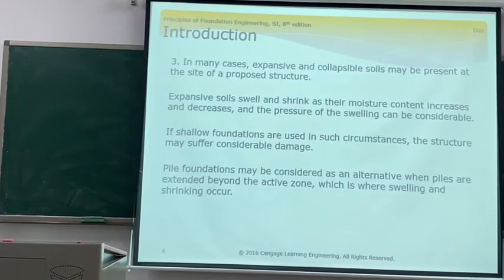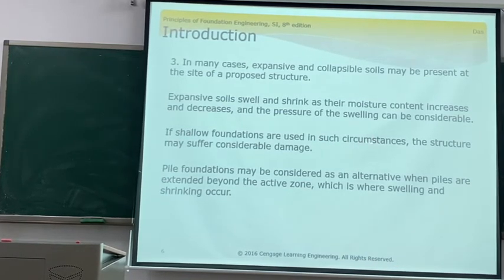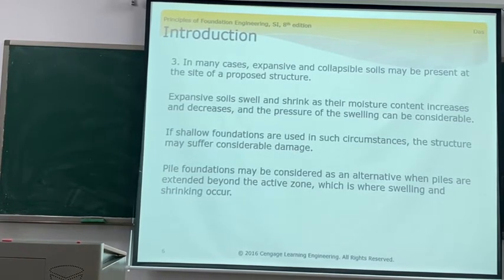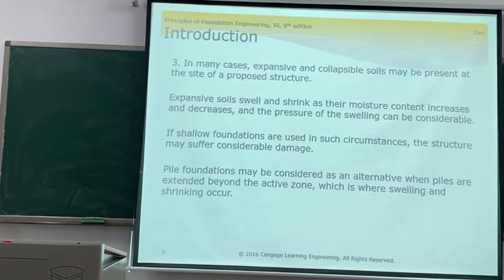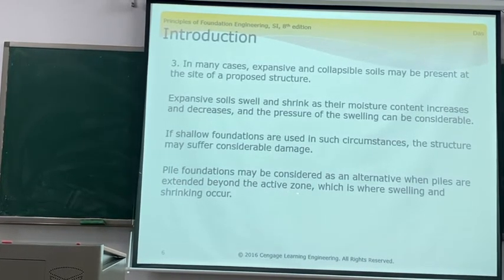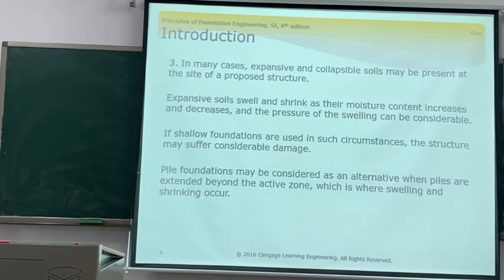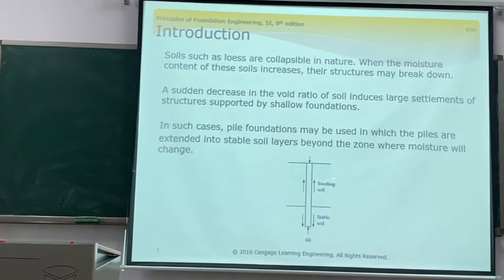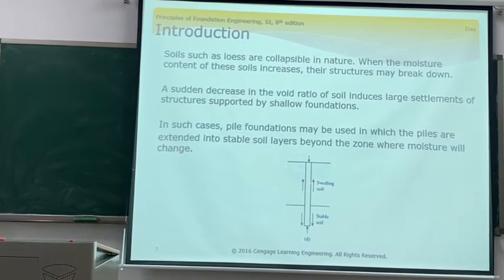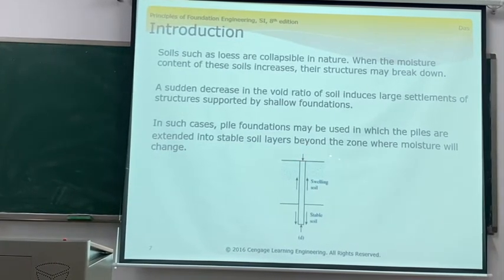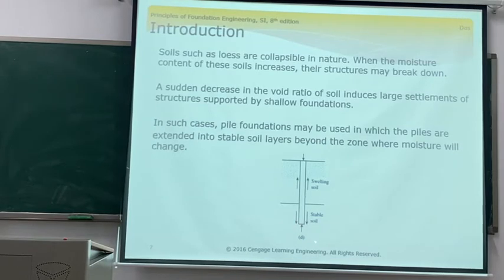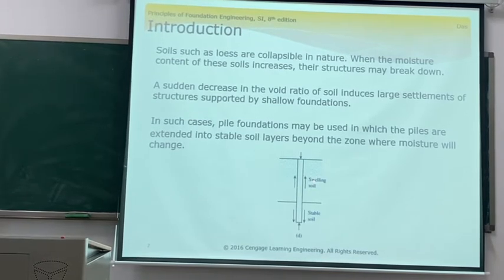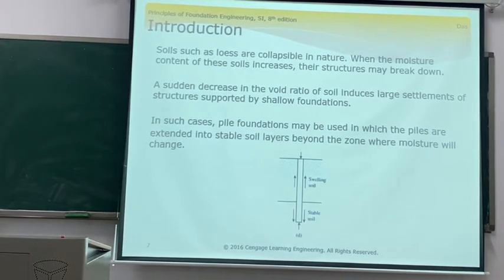In shallow foundations in such circumstances, the structure may suffer considerable damage. So the pile foundation may be considered as an alternative when the piles extend beyond the active zone. So we can transfer the load to the stable soil layer and reduce the influence of this soil when it is expansive soil.